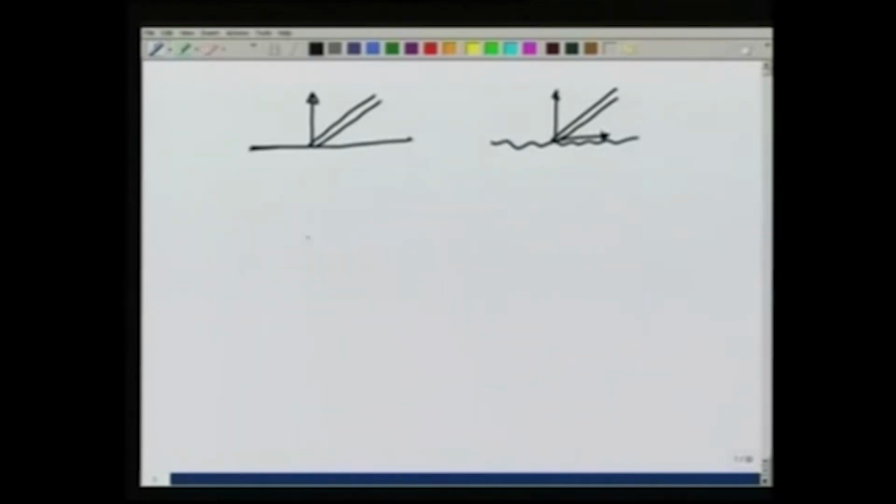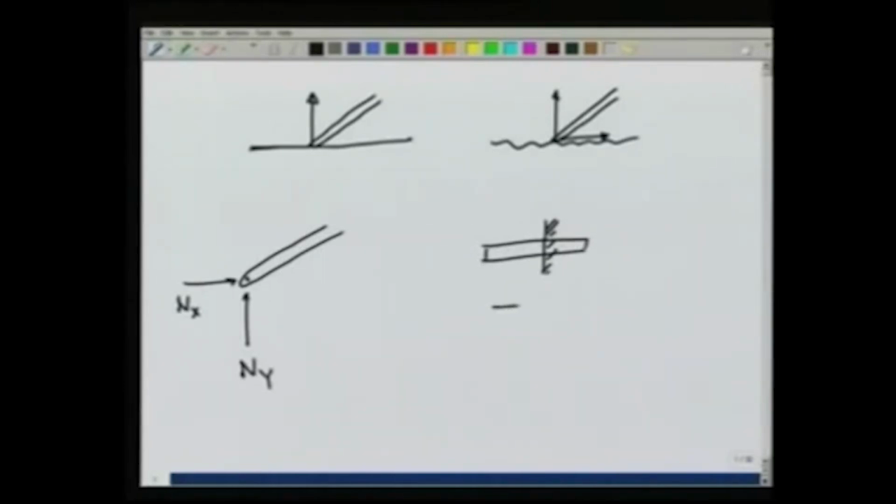Then we looked at a hinge joint and saw that this can apply force both in the x and the y direction, and we looked at fixed or welded joints, and we saw that this is capable of applying a force in the y and x directions, as well as it can create a torque. We had solved examples using this, this and this.